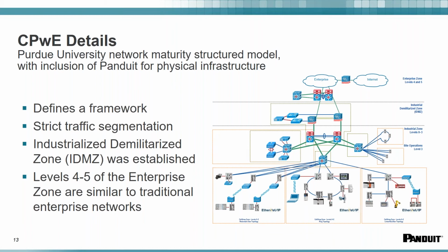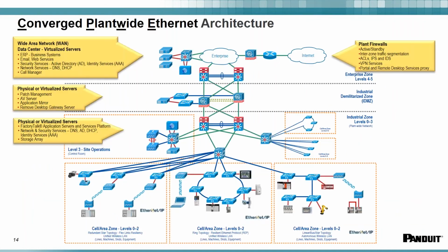And the way they did it is by simply adding these demilitarized zone devices that basically stop certain traffic from reaching the enterprise layer, either because it's not needed or because it simply could jam the network at the enterprise. It's simply the way they separate the different architectures. So that's logically how an architecture of a control system is placed within the enterprise communication architecture.